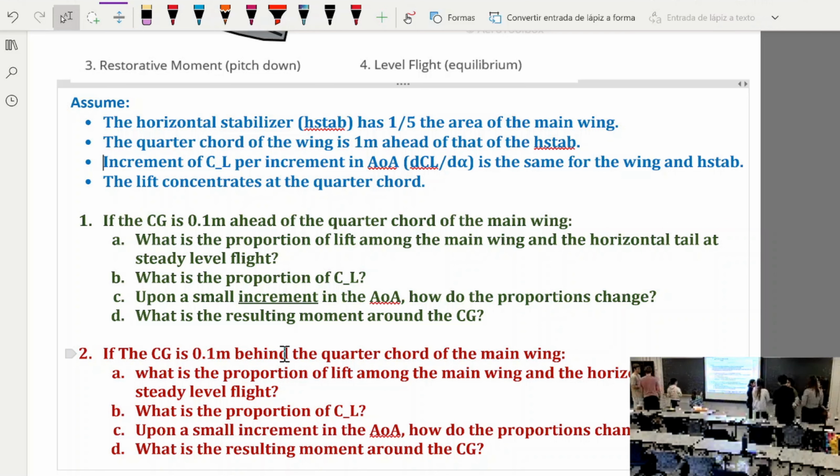So basically, you're gonna get the translational acceleration upwards, but the rotational acceleration nose down. Can you say it again? Because the lift in the main wing increases, the downforce on the tail decreases. So the resulting total force is going to be more than the gravitational force, which didn't change.